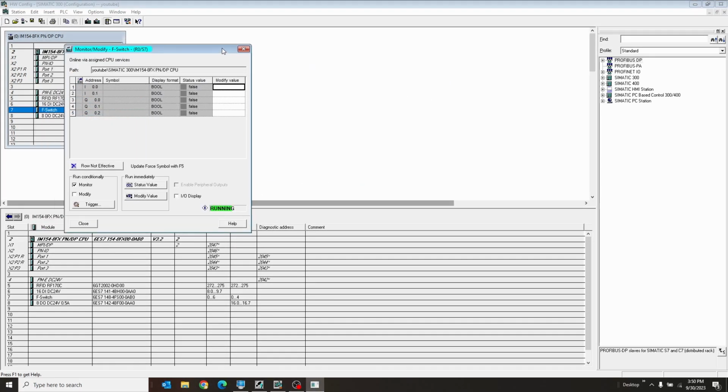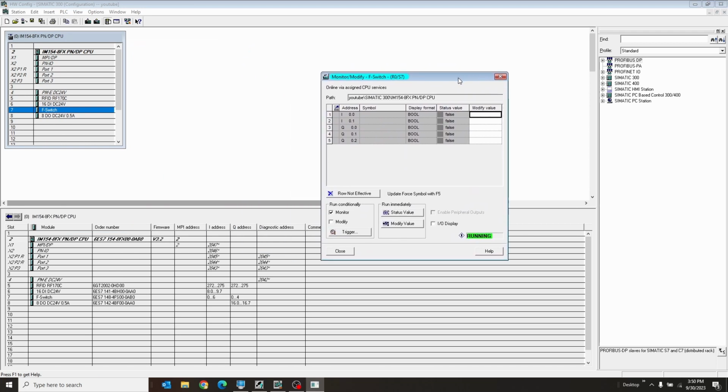Okay, going back over the wiring was just fine. I eventually figured out what the problem is, and I'm glad I'm making these videos because I will forget this later again. So anyways, my e-stop is unpressed, but I don't have my input here. So I looked at the wiring. The wiring was good. The two channels were there. The e-stop itself rang out properly.